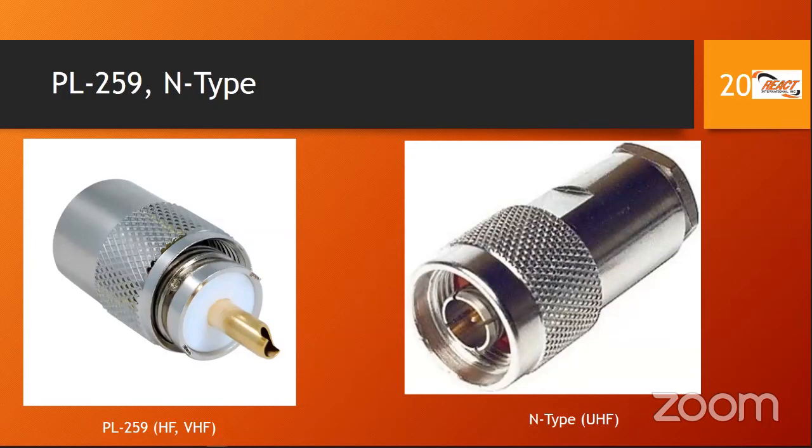Yes, Andrew, very good question. There's nothing wrong with thinner cable. There is an application. For mobile applications, for instance, you're using a mobile antenna with a mobile radio, and the length from the radio to the antenna is what, 10 feet? Certainly not 100 feet. So it's a very short run. And remember, you're trying to get from the outside of your vehicle, so you're probably going through the trunk, or the doorway, or some firewall where you don't want to punch a very large hole. So you can use the thinner cable.